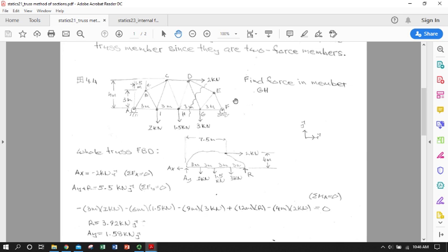So if you think about placing your section in such a place that you will be taking a moment analysis of the resultant section, that will usually lead you to the best placement of sections for your analysis ease. Otherwise, as long as you cut it, you will be able to crank through your equations of equilibrium and get to it eventually. So that is now it for our discussions of trusses. At this point, the ball is in your court to practice. The more you practice, the more efficient you'll get.